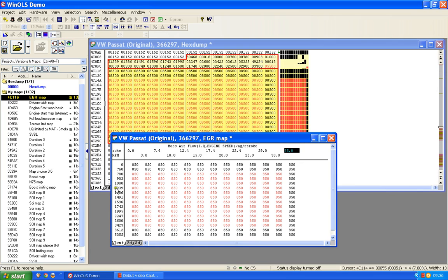And I could do the same, I could change the revs per minute axis. Now sometimes the only thing you need to change is the axis and not the data at all, because sometimes all you want to do is shift the value slightly, especially for quantity of fuel, to allow a little bit more fuel to flow, or to just change what is occurring at that particular amount of fuel. So sometimes this is all you want to change and you don't want to change these. But hopefully this little guide has given you a clue as to what you can or you can't change.